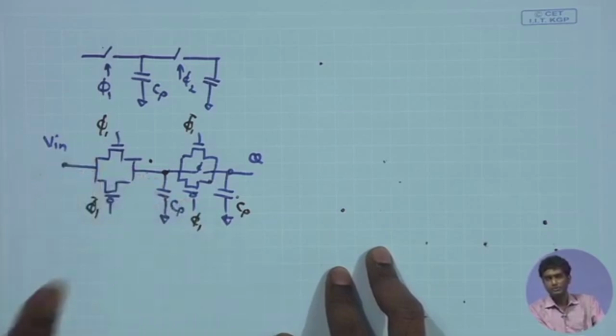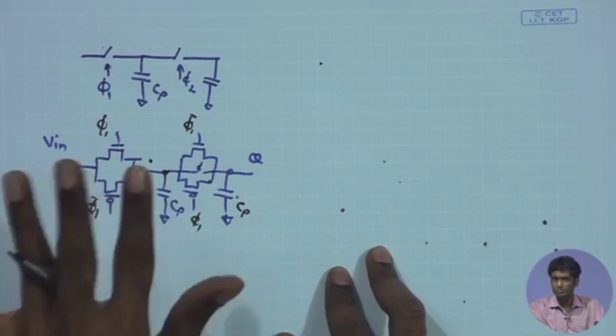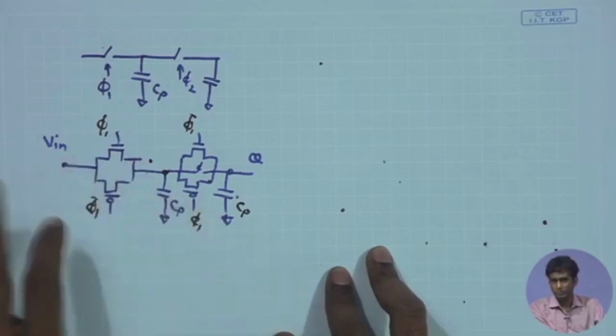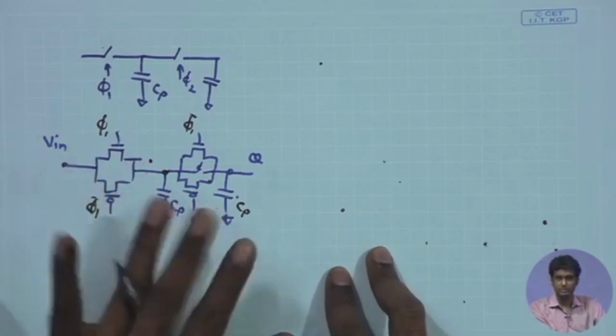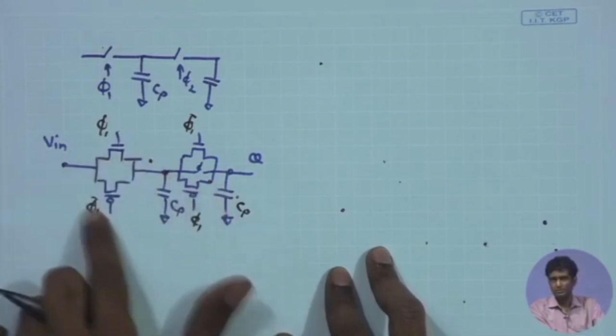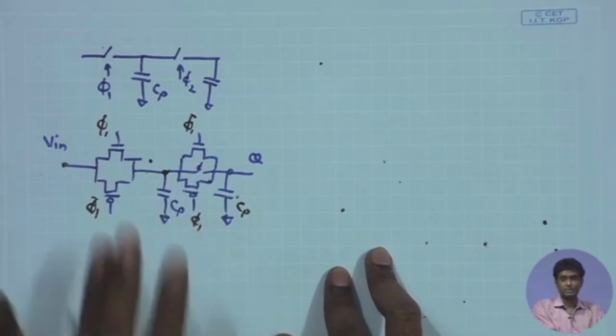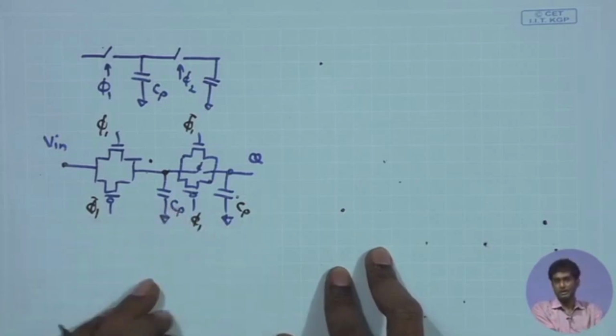For analog blocks, they are fewer in number in the front end, so you need a few big capacitors, whereas digital units can be large in number. So, you need a huge number of registers and flip flops, and of course, we cannot afford to put additional dedicated capacitors, we can rely on the MOSFET capacitor.